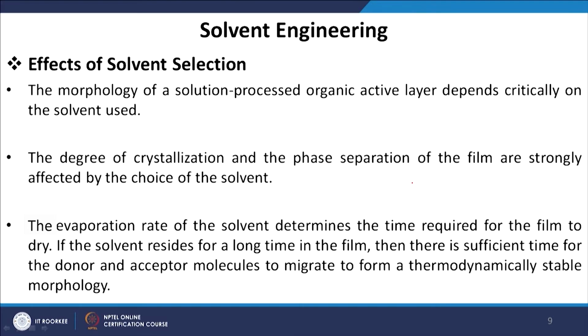Now, what are the effects of solvent selection? The morphology of a solution processed organic layer depends critically on the solvent used. The degree of crystallization and the phase separation of the film are strongly affected by the choice of the solvent. As I said, as the solvent is different, the dielectric constant is different. If the dielectric constant is different, then the polarity is different. Now, we can choose two solvents where the dielectric constant difference or the polarity difference is small, and we can choose two solvents where the difference is very large.